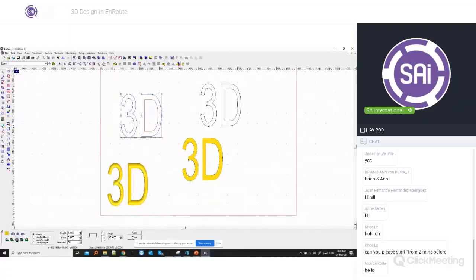and we'll use the round relief for this. If you use the normal type of application, then the height of your relief would be defined by the angle that you set up here. We can choose a resolution as well, which will define the DPI of the relief.